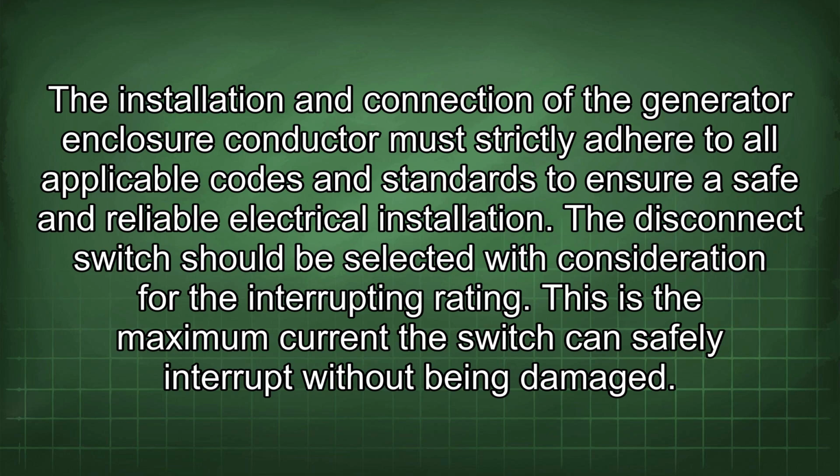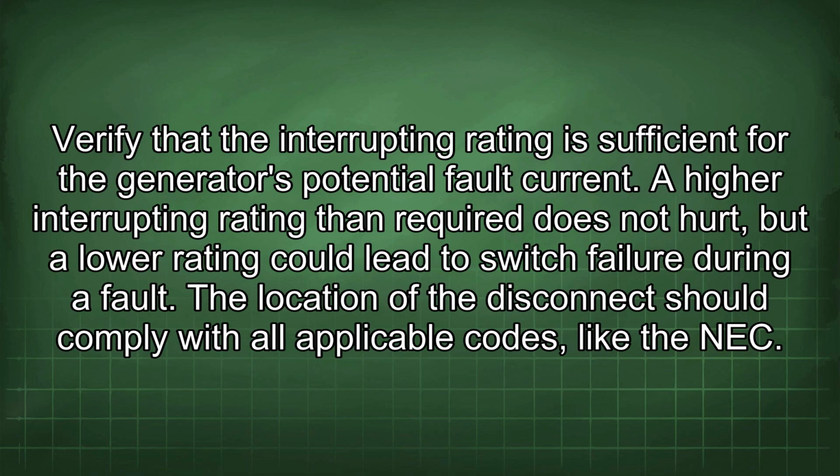This is the maximum current the switch can safely interrupt without being damaged. Verify that the interrupting rating is sufficient for the generator's potential fault current. A higher interrupting rating than required does not hurt, but a lower rating could lead to switch failure during a fault. The location of the disconnect should comply with all applicable codes, like the NEC.